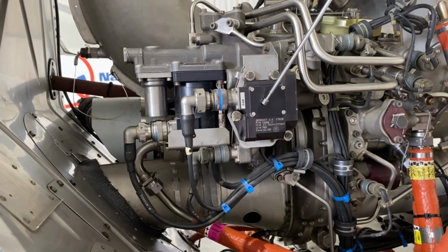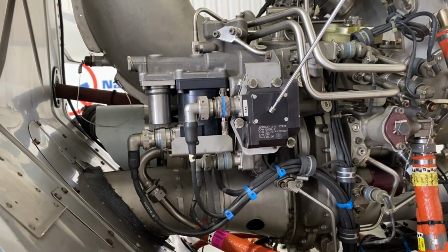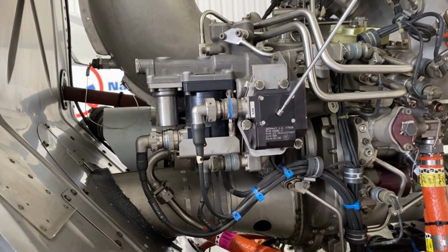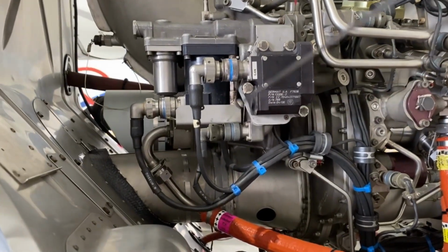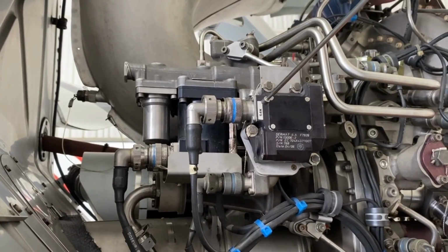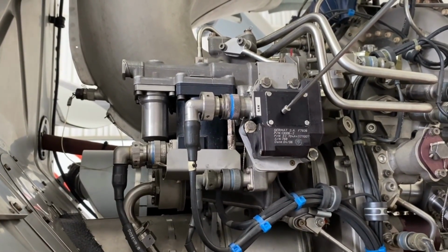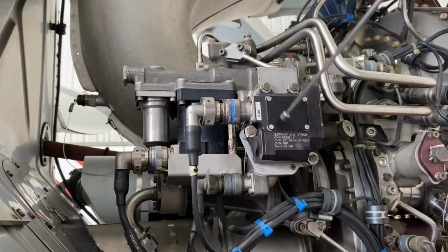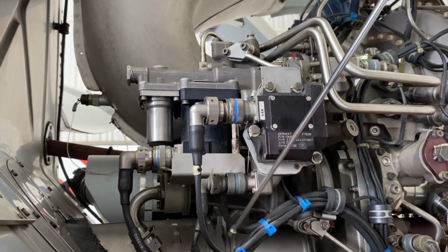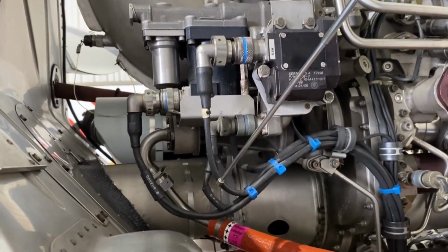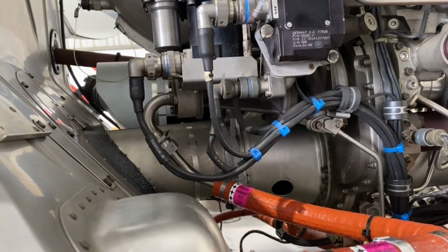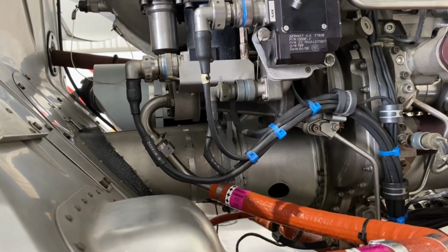But the manual override only operates in response to a drop in N2, which is mechanically connected to the helicopter's rotor. Here we have a plug, which indicates the neutral position of the manual override. The computer needs to know if the manual override is in the neutral position during normal operation. And this signal, which has an internal switch, is also sent to the ECU system, to the FADEC system. Here we have channel A, channel B, and here we have the manual override.